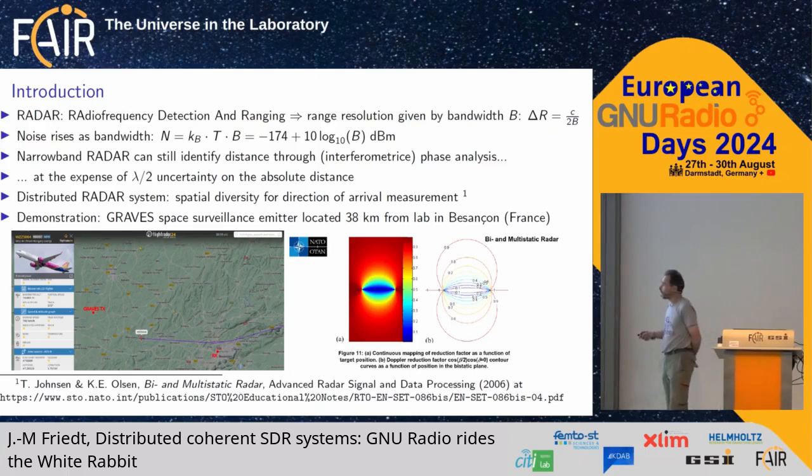Another application: the laboratory I come from is a time and frequency laboratory, so our activity is to have ultra-stable clocks, ultra-stable oscillators, with the ability to timestamp events with high accuracy, meaning sub 100 picosecond. One activity here is to use these high stability clocks for detecting fine frequency shifts. The frequency shifts that we're interested in come from a moving target. If a target is moving, then you have Doppler shift. And if you can have a fine Doppler shift measurement, you have a high accuracy velocity measurement.